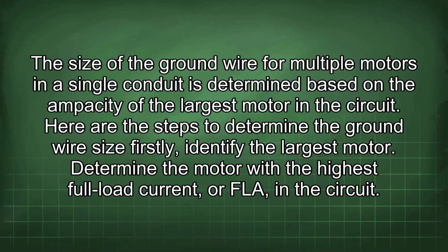The size of the ground wire for multiple motors in a single conduit is determined based on the ampacity of the largest motor in the circuit. Here are the steps to determine the ground wire size.